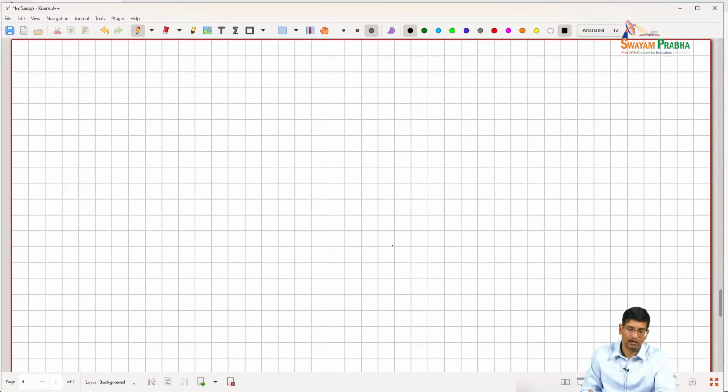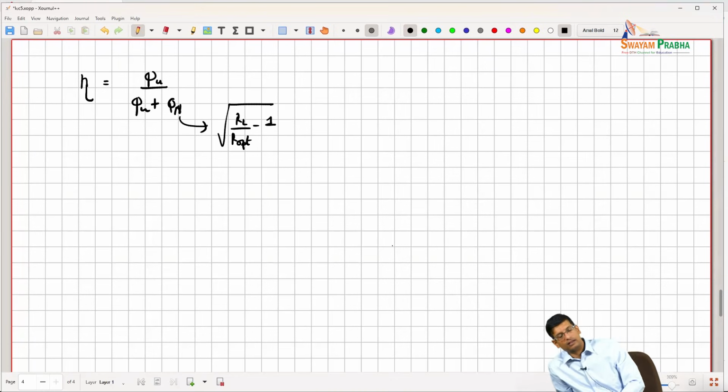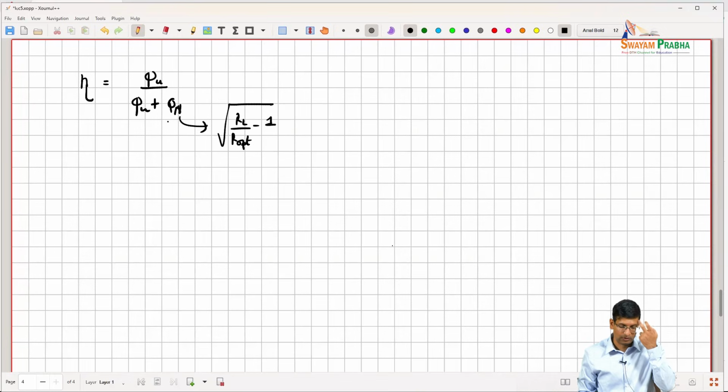And if we use the simple shunt series sort of matching, the efficiency of our matching network is QU divided by QU plus QN, right? Where this QN depends upon RL over the real part, let's say, of the Ropt that we want, minus 1, right? So if I try to do a very large transformation, then I can see that QN is going to be large, right?